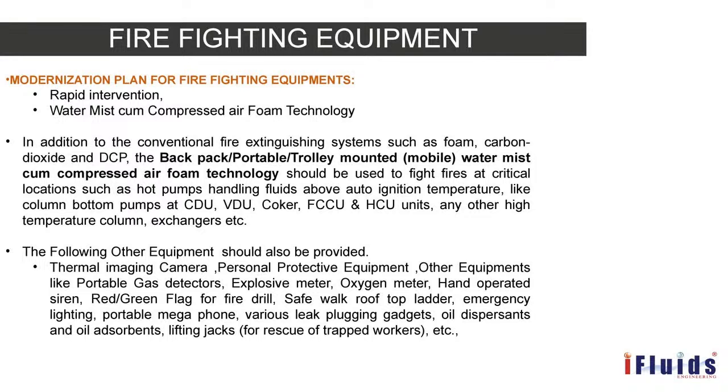This additional water mist compressed air foam technology has to be provided at critical locations which handle hot pumps, that is, pumps handling fluids above the auto ignition temperature, like the column bottoms of CDU and VDU, the coker unit column bottom pumps, FCC unit bottom pumps, and HCU unit column bottom pumps.